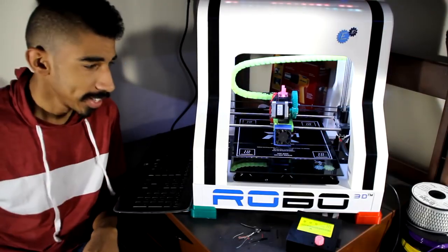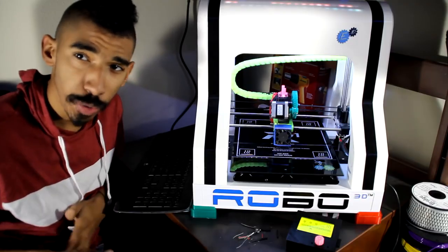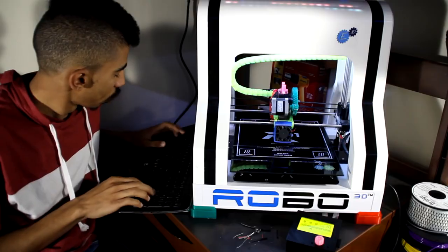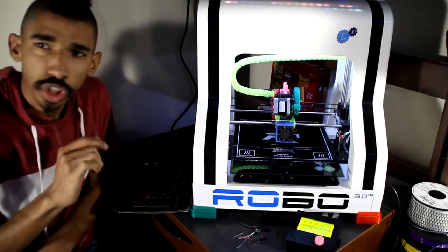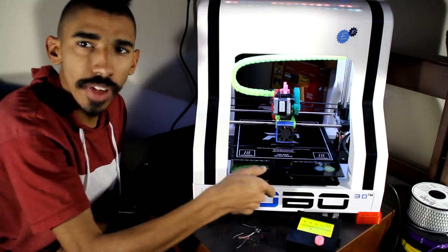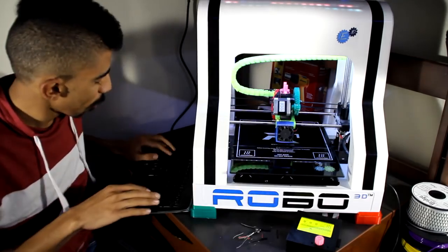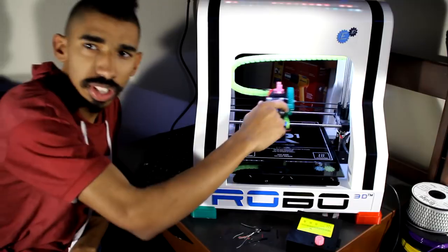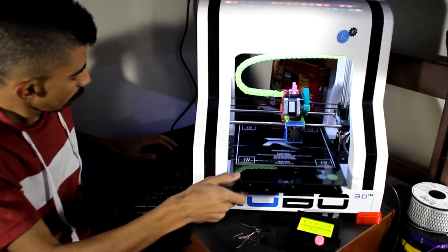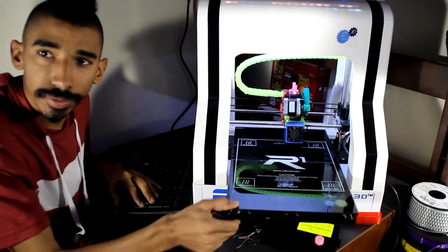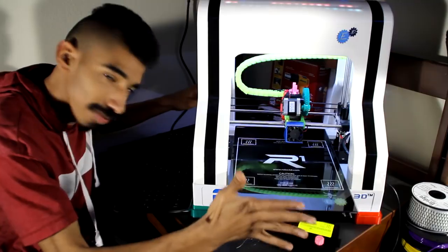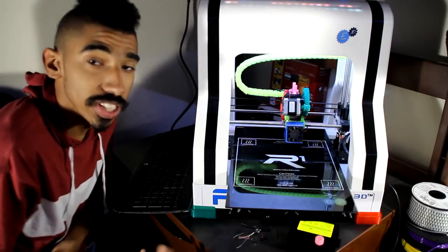Another useful command is an M18. After you implement any codes with G1, like G1 Z10 and G1 X5 Y5, because I've used every single axis, I can't move any of the individual axes. To disable motors, it's an M18. This will disable the motors so you can move them around. And if you put an M17 in there, the motors will lock up and re-engage. So now I can't move that unless I make the motor skip.